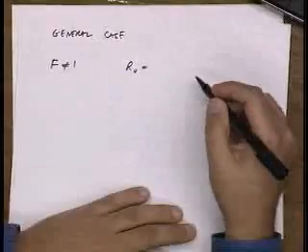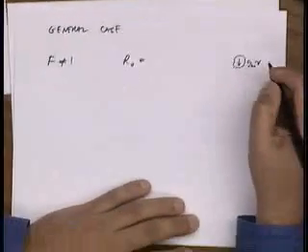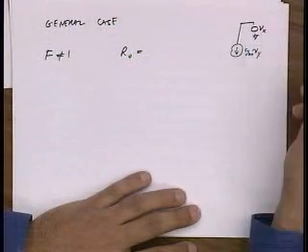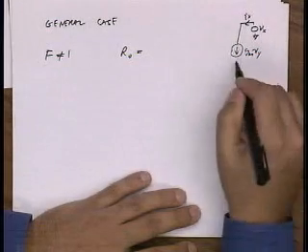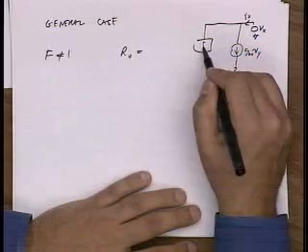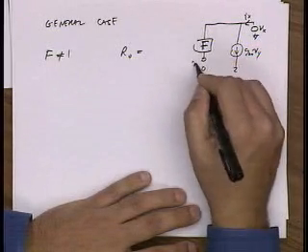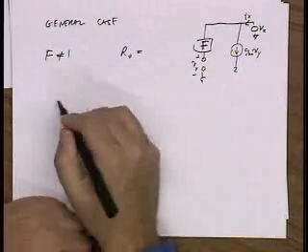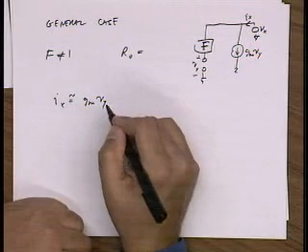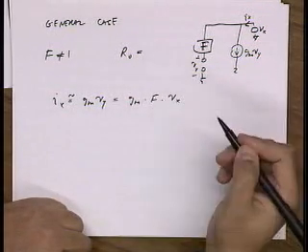So let's just draw a simple equivalent circuit. Let's say I have gm Vy. So let's say this is my test source Vx, Ix. And I have a feedback circuit, let me call this capital F, that generates Vy. So Ix is approximately equal to gm Vy, which is equal to gm F times Vx.